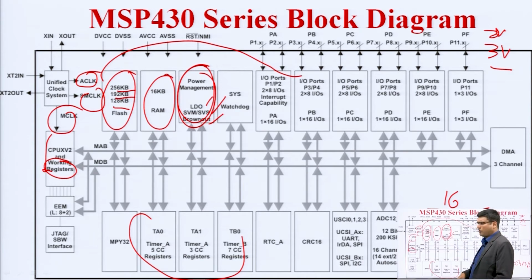What is brownout? Brownout means there is a significant drop in the power supply. If the power supply is not available as per the requirement, then the brownout circuit will provide the necessary power supply. We can say that it will reset the system. So the system will be reset by the brownout circuit in case of a significant drop in the power supply. This condition of significant drop in the power supply is a brownout condition.